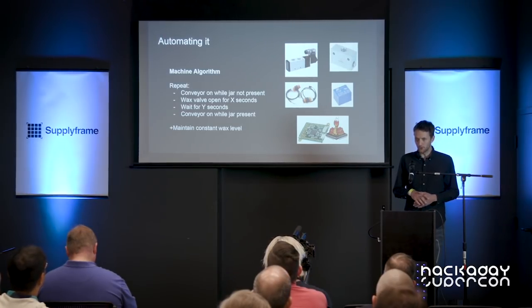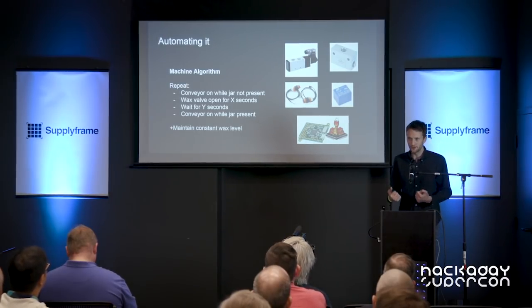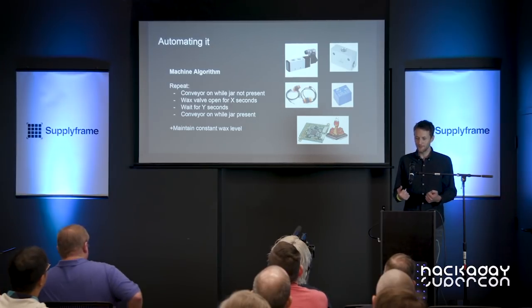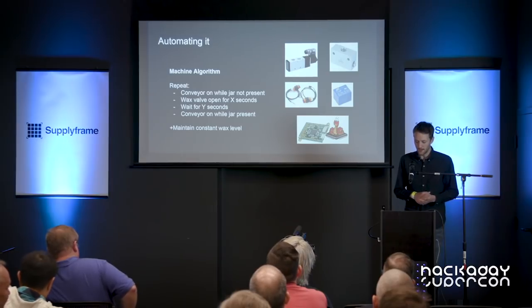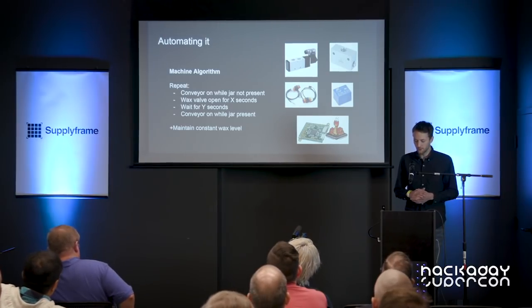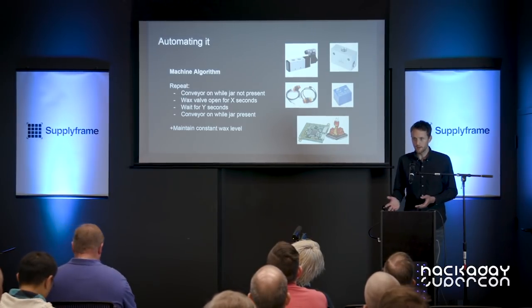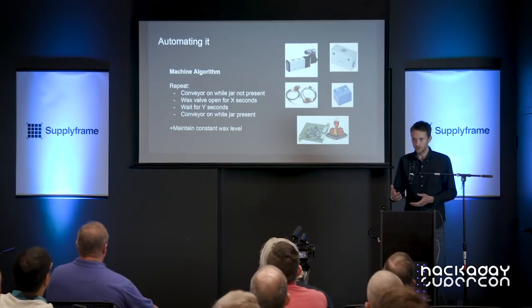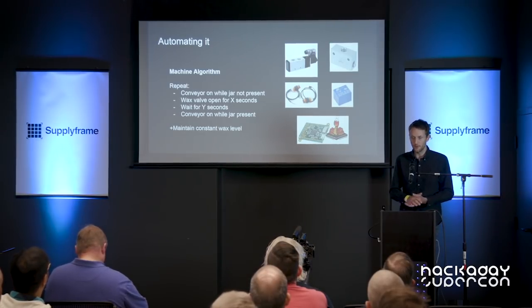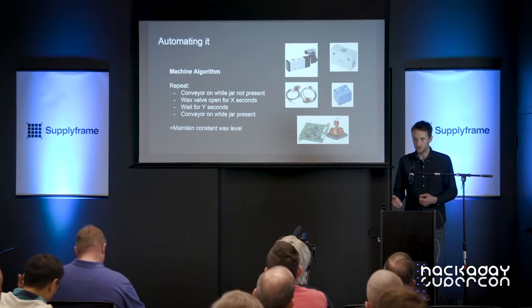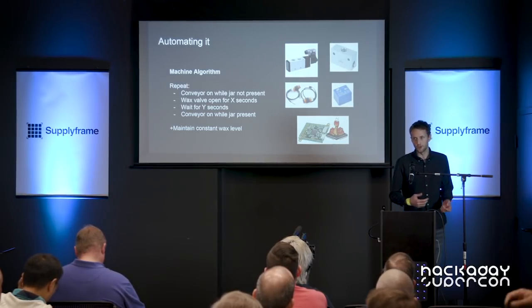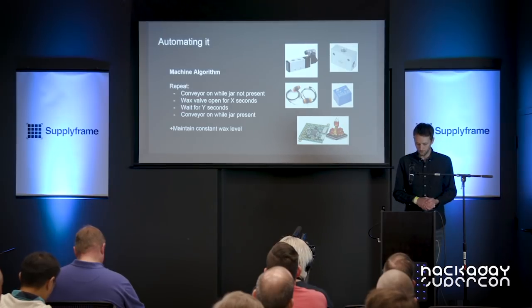This was all programmed in MicroPython. I'm still sometimes feeling the need to justify this decision. I'm not going to do it right now, but perhaps later you can come talk to me about it. This was automated mostly with pneumatic solenoid valves, shuttle valves, basically very simple pneumatic equipment. Everything was installed in parallel to the manual operation, so if something breaks or goes wrong, you can still operate the system manually.